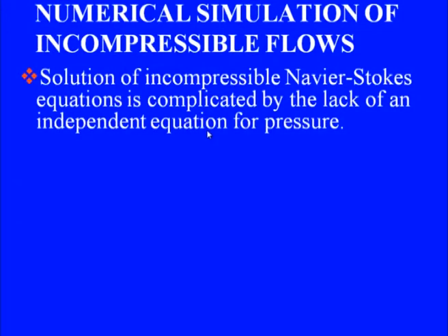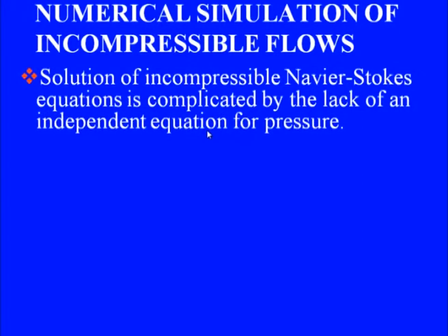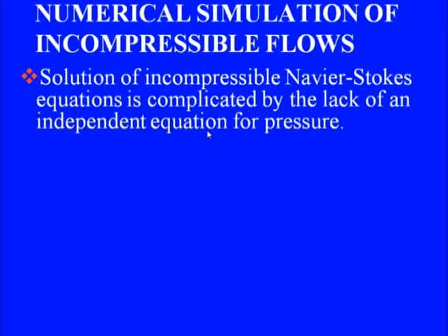Now, let us come to the numerical simulation of incompressible flows. This one problem which we mentioned earlier, that Navier-Stokes equations for incompressible flow involve a pressure gradient term, the gradient of P is there, but there is no equation for pressure, in contrast to compressible flows where pressure can be computed from the equation of state. We do not have any such independent equation for pressure for incompressible flow problems.